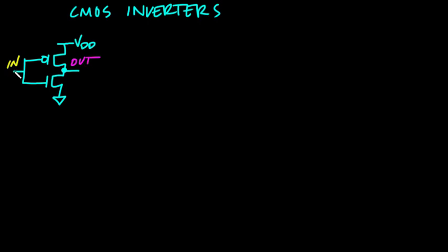Today when we're working with the inverter, we're going to connect the input to a voltage source that looks like a pulse. So this would be something like V pulse if you were working with PSpice, and the bottom of it is going to go to ground. Now what do we connect the output of the inverter to? Well, in real life, the output of this inverter is either going to drive another logic stage. So maybe it'll drive the input of another inverter or many inverters.